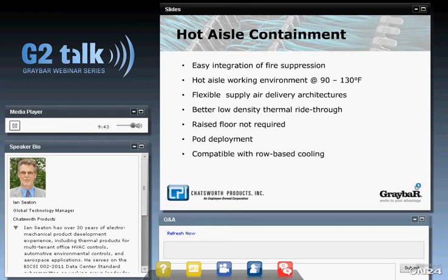The barriers from hot aisle containment are going to abut the surfaces where fire suppression is deployed, creating some separate rooms into which that fire suppression will deliver. If we're on 10-foot centers on our fire suppression pipes, you can probably get 4 or 5 rows of cabinets before you might start facing a clearance issue and have to move those rows. If we're on 8-foot centers on our fire suppression, then it's a non-issue and everything will work just fine.